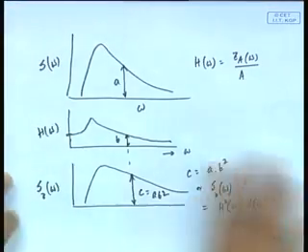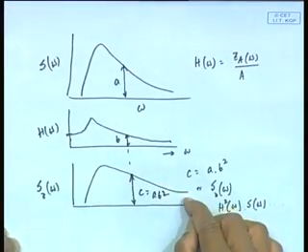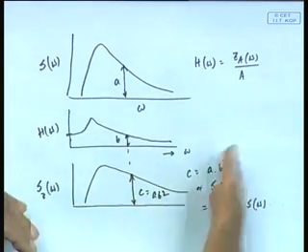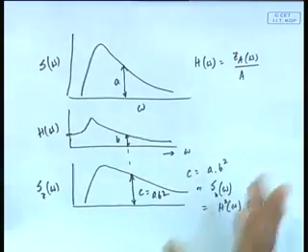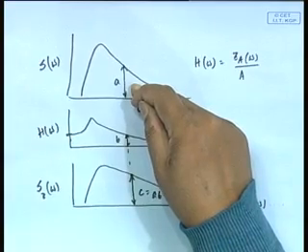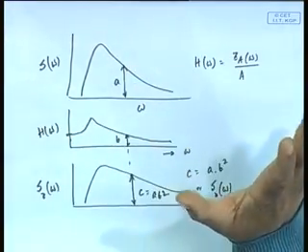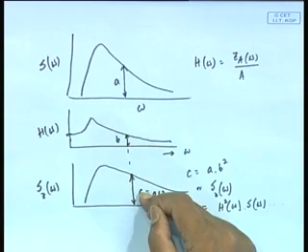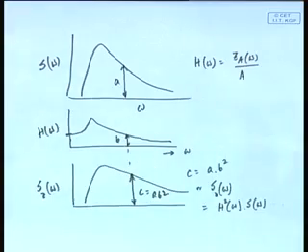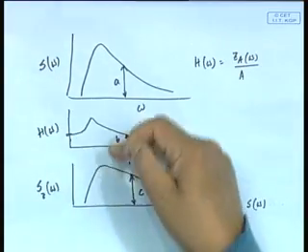Now, having said that, we will find out that this spectrum also satisfies all the statistical quantities same as the Rayleigh distribution, the narrowband Rayleigh distribution. Therefore, we will be able to find the average amplitude of the response, the 1/3 amplitude of the response, and all quantities that I want, just like what I could do for this. Here I could find the most probable wave height in 1000 seconds. I can find this also: the most probable roll angle in 1000 cycles or seconds. Everything is the same, because this graph is assumed to have the same form as this.